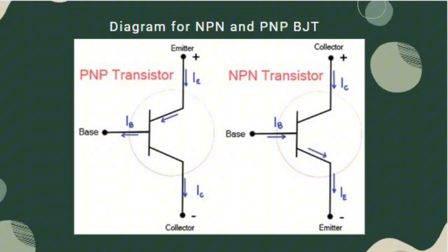In an NPN transistor, current flows from collector to emitter with electrons as the majority carriers. In a PNP transistor, current flows from emitter to collector with holes as the majority carriers. The base must be correctly biased to allow current flow. BJTs are called bipolar because both electrons and holes are involved in conduction. This terminal arrangement makes the BJT useful for amplifying signals. For example, a microphone signal to drive a speaker can be amplified using a BJT.